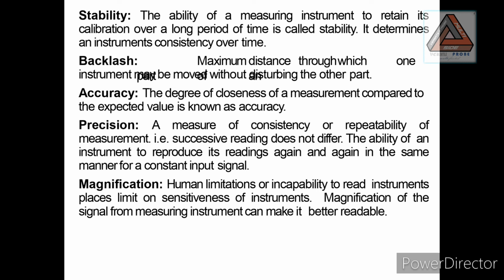Factors affecting the environment: temperature, humidity, atmospheric pressure, clean surroundings and minimum vibration enhance precision. Temperature equalization between standard, workpiece and instrument. Thermal expansion effect due to heat radiation from lights, heating elements, sunlight and people. Manual handling may also introduce thermal expansion.